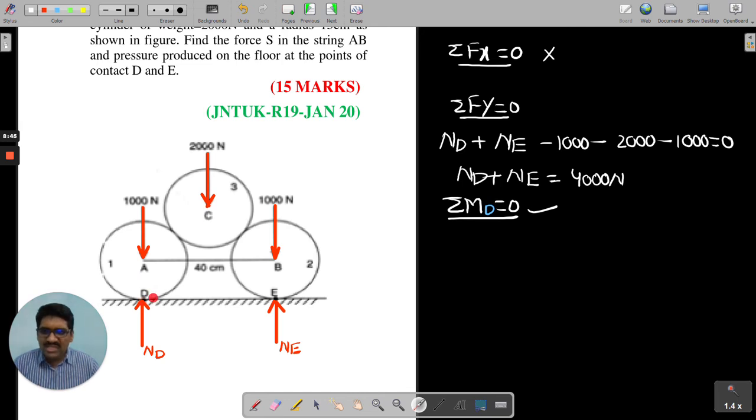Over. Now with respect to point D, what is the moment of 2000? With respect to D, this 2000 is providing which direction moment? Clockwise moment. With respect to D, it is providing a clockwise moment. Okay, but what is perpendicular distance? So this is the force, all of you. This is the force, and this becomes distance. You can check, all of you. Okay, so this becomes the line of action of the force. Can I say, all of you, this will become your perpendicular distance or not? Yes. Okay, and this producing in which direction? Producing moment in clockwise direction.